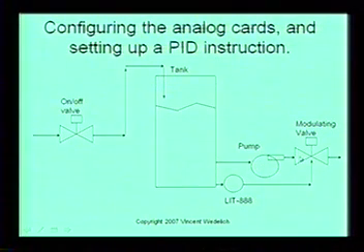It's wide open. So we modulate this valve fully open or fully closed. If we modulate the valve fully open, the pump is strong enough to push that water out so fast that it'll drain this tank. And ideally, when this valve is on, there's enough water coming in to fill the tank. But there's not too much water going in, and there's not too much water coming out. So the modulating valve takes care of that.